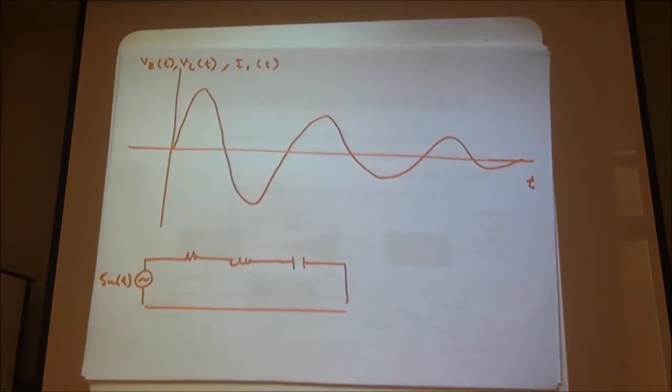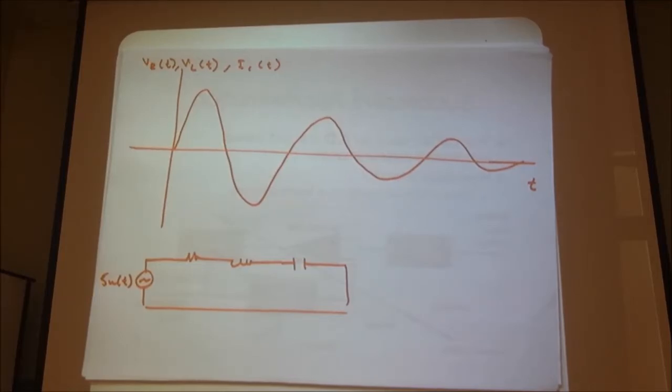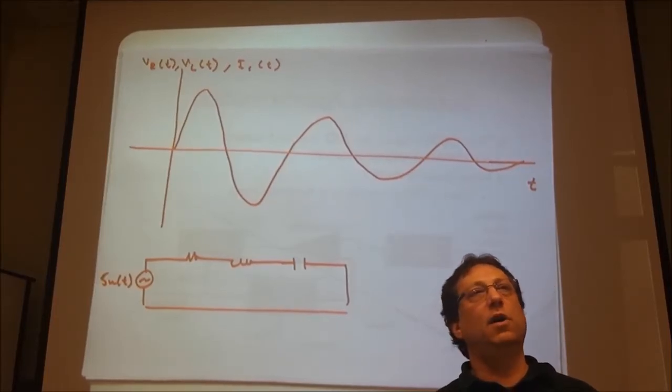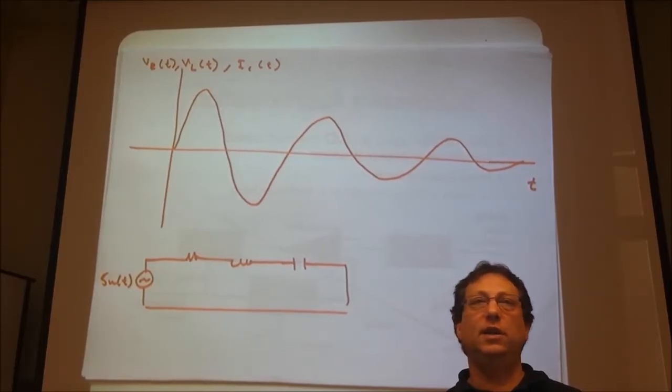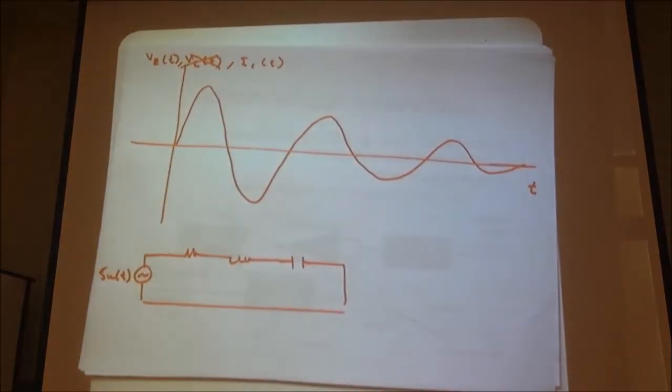Now, actually, one of these we can rule out. Which one is it not? VS. Well, it's not VS, that's true. But no, out of these three, one of these it's not. For this particular source, what is it not? This goes back to our initial condition. It can't be VL, because when you do the KVL analysis, our initial condition, again from problem 1 on the homework, the voltage across the inductor is not 0 at t equals 0. And actually, I've had that as a test question before, so it's not that one.